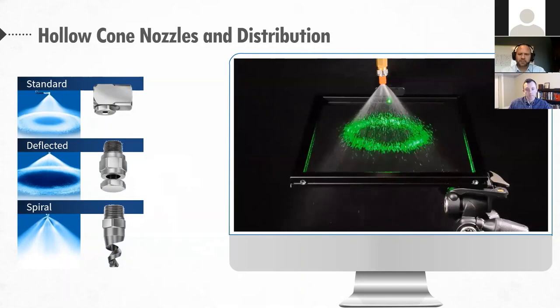Yeah, so the way the hollow cone works is, this is not a precision spray, right? This is a chunky spray that's designed to reliably atomize and break up the liquid. Typically operating at lower pressures, and imagine a liquid core coming through that nozzle, and the spiral actually shaves off the outer edges of that liquid core until it's left with nothing left at the bottom. And so you end up with this spiral pattern. Whatever you're spraying onto, typically larger droplet size, but the passageway through the nozzle is much larger than any of these other options, which require more of a pressure-driven atomization.